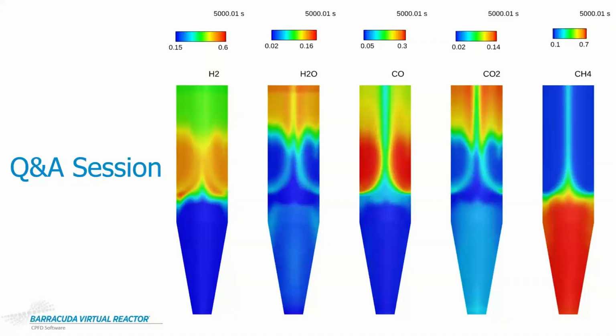Those include a continuous particle feed, but we do have a lot of flexibility in terms of if you have a non-continuous feed. If you're pulsing in particles that might be over smaller time scales, or that feed is not steady, that's something that certainly can be implemented. Also, the SFF editor is a great way to do that. And so we're able to use Barracuda inputs to define flow rates over certain ranges of time. I think that might address the question.